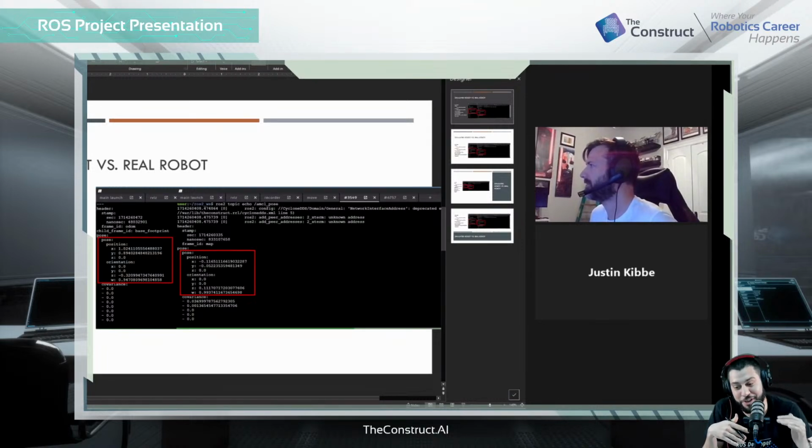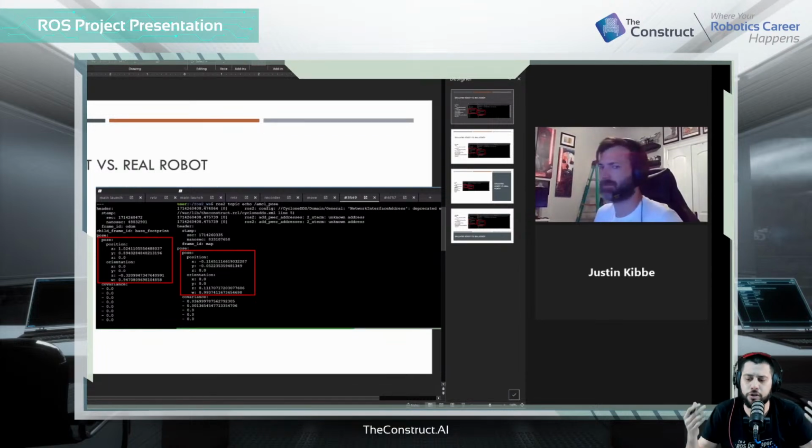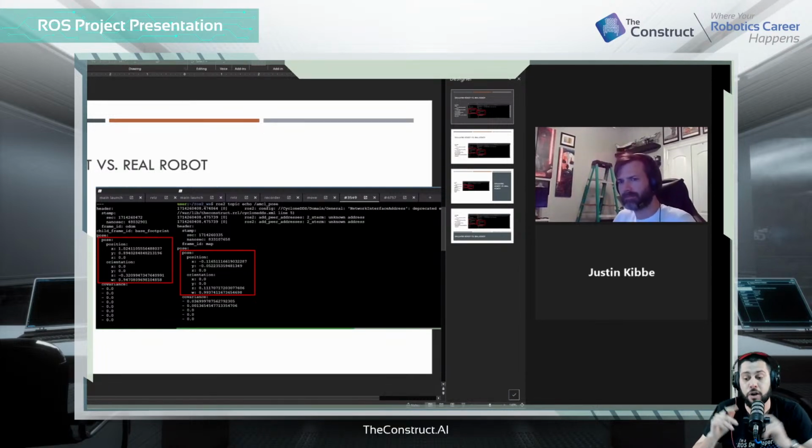And the solution is moving to the AMCL pose. Yes, because what AMCL pose does is it basically publishes the map to odom frames, because when you start your robot or your simulation, you should always have your odometry frame, which is different than the odometry topic, right?